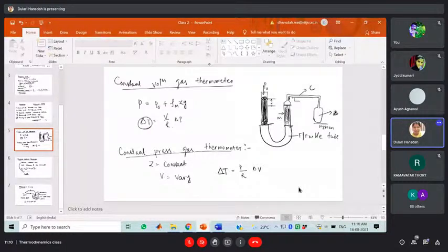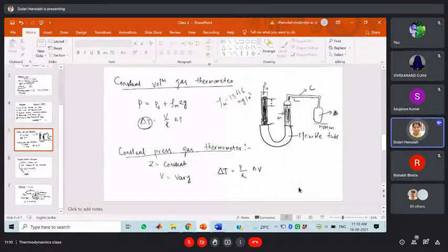Density is 13.6, that is, 13.6 times 10 cubed, 13,600 kg per meter cube, right? So in this case, how much height are we taking? Z we are taking as 760 mm of mercury, right? Am I right? Yes, okay. So when Z is usually 1 meter, then rho m g Z will be 1.3366 bar. Later on, I will discuss this in your pressure chapter.